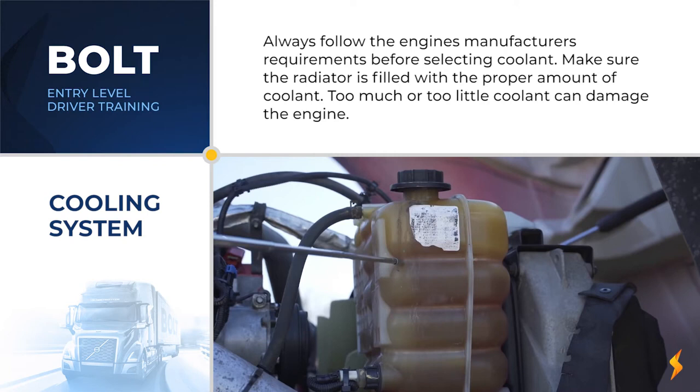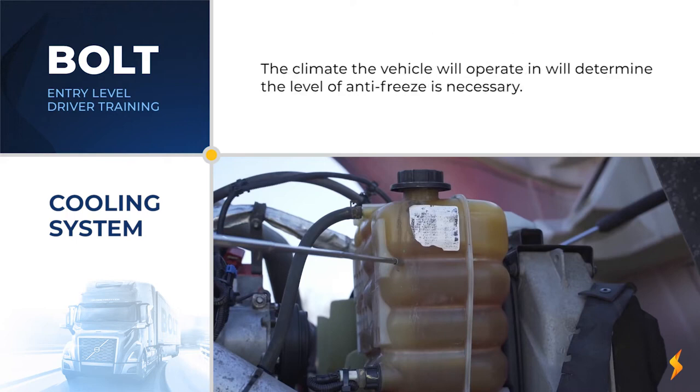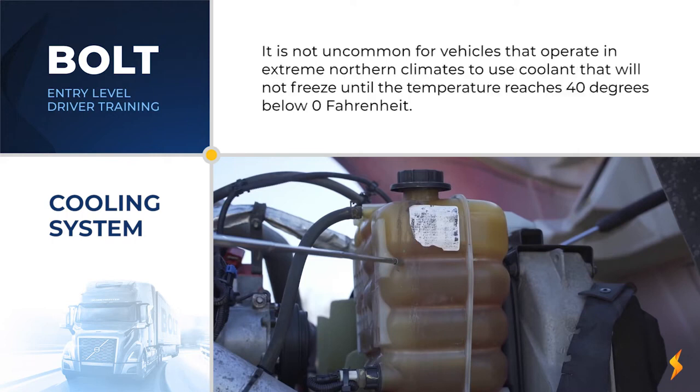Always follow the engine manufacturer's requirements for selecting coolant. Make sure the radiator is filled with the proper amount of coolant. Too much or too little coolant can damage the engine. The climate the vehicle will be operating in will determine the level of coolant antifreeze protection necessary. It is not uncommon for vehicles that operate in extreme northern climates to use coolant that will not freeze until the temperature reaches 40 degrees below 0 Fahrenheit.